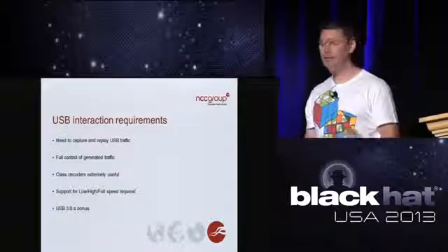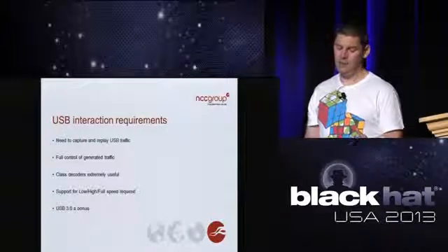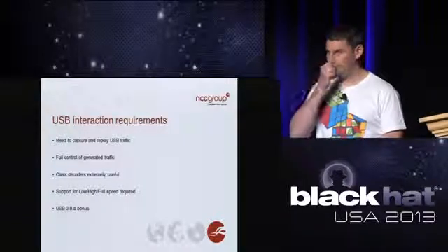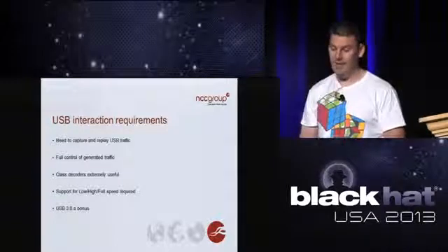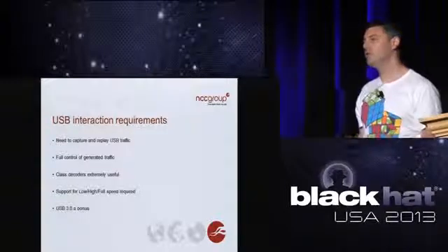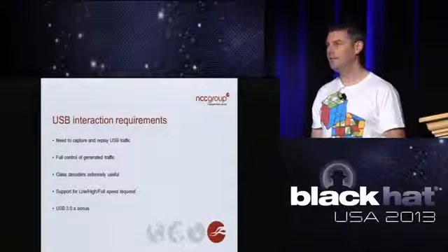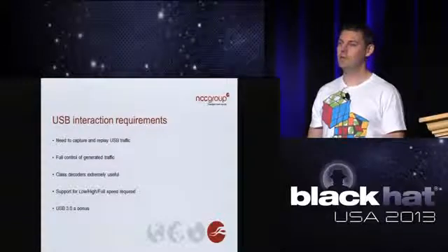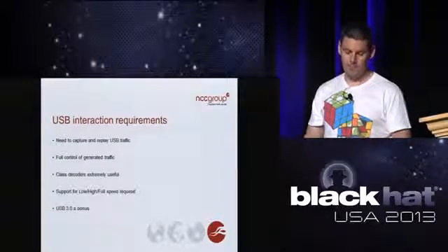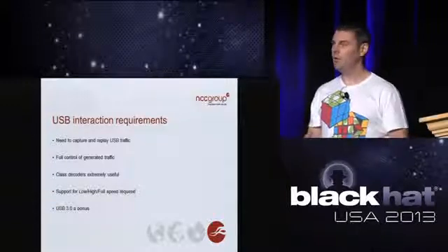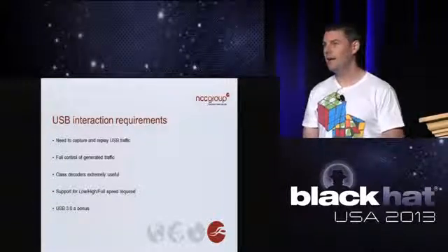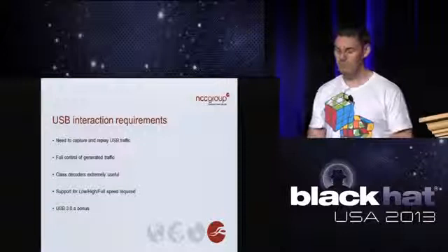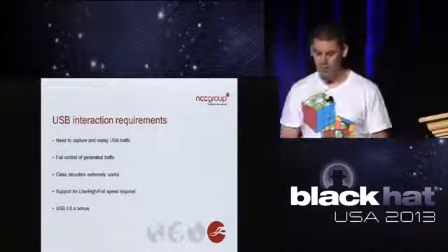The ability to decode separate USB classes is very useful indeed. There are separate specification documents for all the different USB classes and the class-specific traffic associated with them. So with our system that we're using, if we've got something that will automatically decode that so that we don't need to go through and read the spec every time we're trying to work out what's going on, that's really useful.